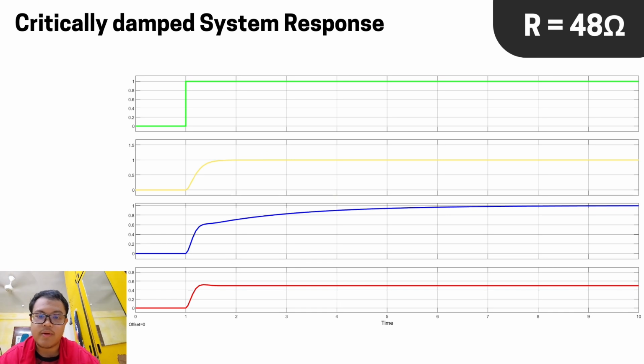Similar to before, we'll give the step input and we'll check each system's response. For the open loop system, the rise time is very quick and the settling time is almost zero, as no values oscillate around 2% of the gain 1. This also happened in the closed loop, which is the red line, but similar to before, the output will be half of what is intended. Now, the PID controller keeps on oscillating until it gets the gain that it wants, which is 1.